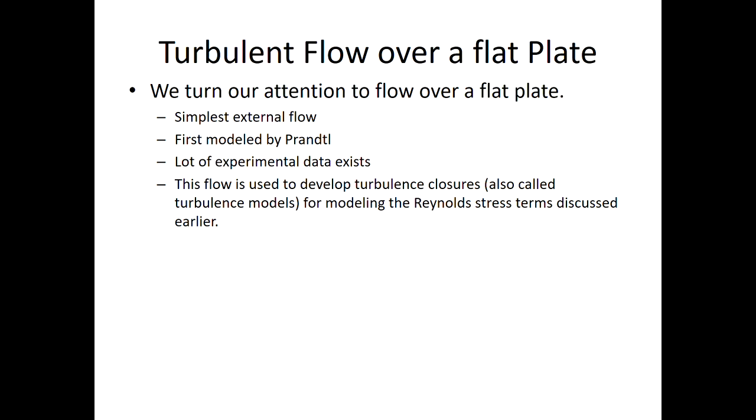Ever since Prandtl started looking at it in the early 20th century, there have been thousands of databases available. They have detailed velocity fields, fluctuating velocity, time average velocity, you name it. Therefore, if you're developing a turbulence model, also sometimes called a turbulent closure, for modeling the Reynolds stress terms discussed in the previous slide, then such flows are very, very valuable, very, very useful. So we are going to work with flow over a flat plate for the rest of this sequence of slides.